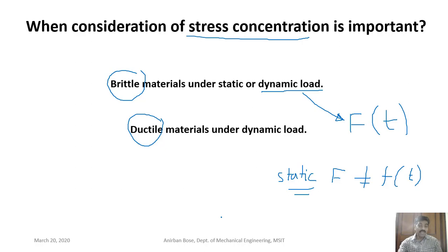Second point, if it is a static load, then in case of ductile material it is not so important. That means stress concentration can be ignored under static loading for ductile materials.